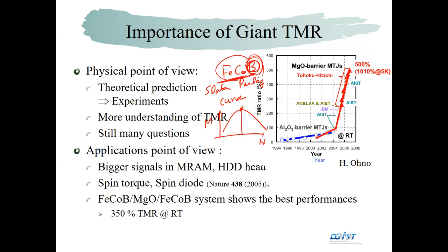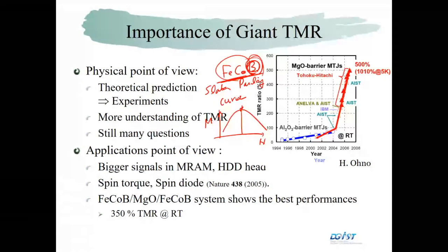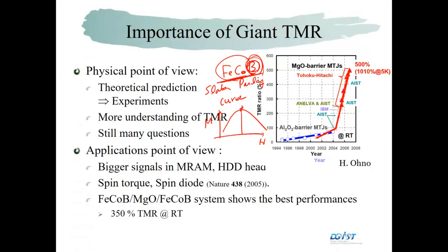So it is questioned what the contribution of boron in a TMR is, because the boron is diffused out and segregates at the interface. And the interface is very important because the tunneling depends on the interface band structure. But the role of boron at that interface is far beyond our simple model. It requires many very careful band structure calculations. Okay.